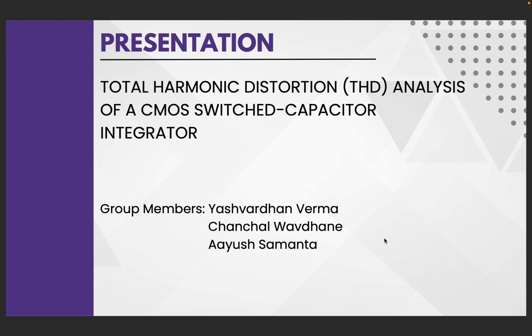In this project, we have designed a switched capacitor integrator in 180 nanometer CMOS technology, implemented it using Cadence Virtuoso, and then analyzed how its harmonic distortion varies with frequency. This helped us understand its filtering capability and real world performance limitations. The main goal was to verify whether the integrator behaves as a low pass filter or not.